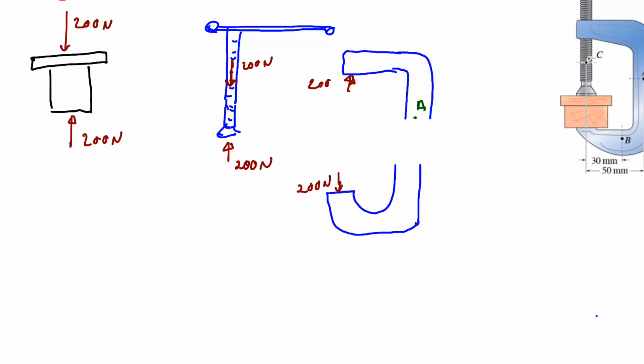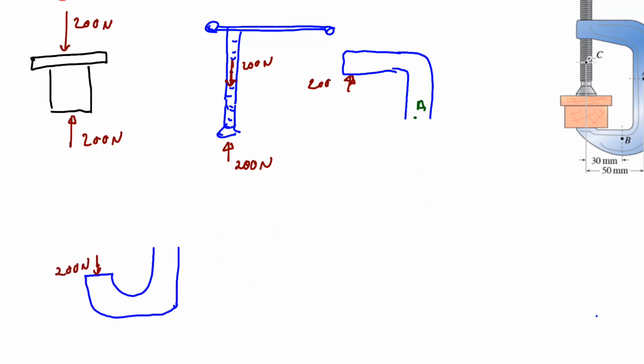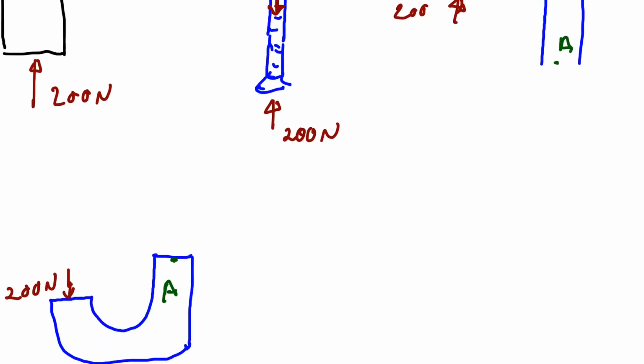So if I cut that and move that down below, we can finish up our free body diagram at this location. What we have at this location then again is our internal forces. Our normal force is always perpendicular to our cut. That is our N. I'm going to call it N sub A because it's at a specific location. We have a shear force.